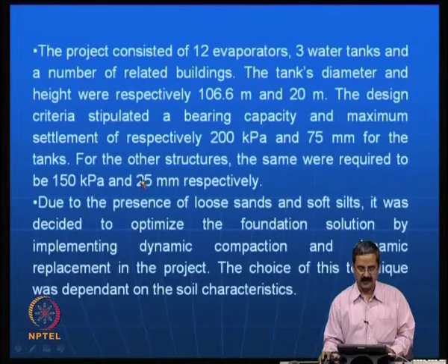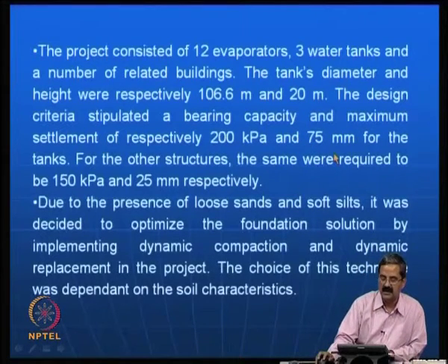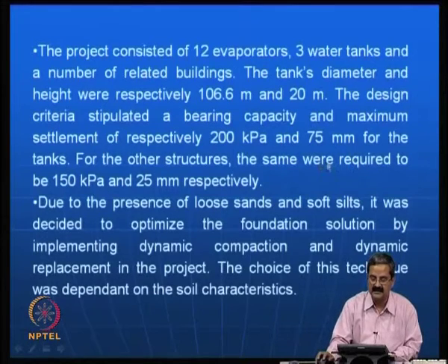You can see that for the water tanks they had 200 kPa as the bearing capacity and 75 mm as the settlement. For other structures, the requirement was 150 kPa and 25 mm respectively. The water tanks could be a little higher, it may be a raft type of foundation, but in the case of isolated footings you should have a settlement of 125 mm or something. So it is very important that the whole area needs to be stabilized.